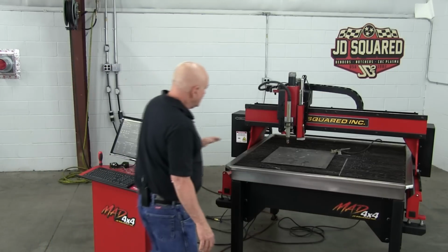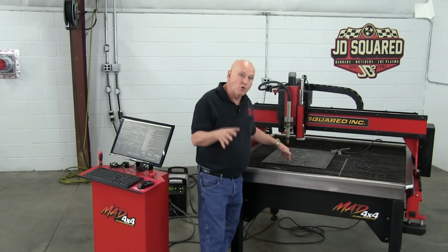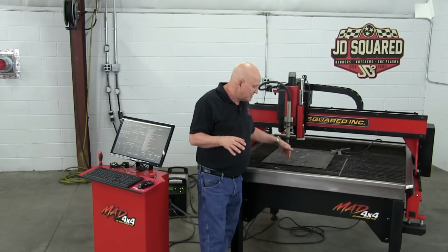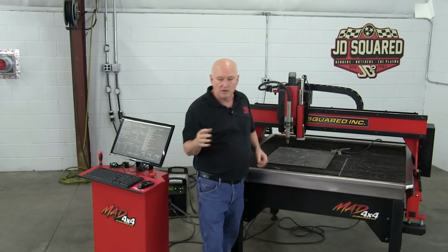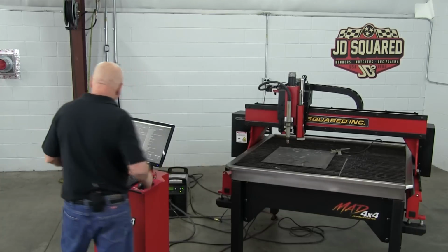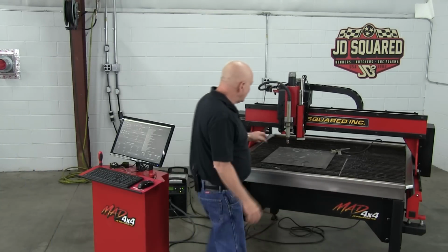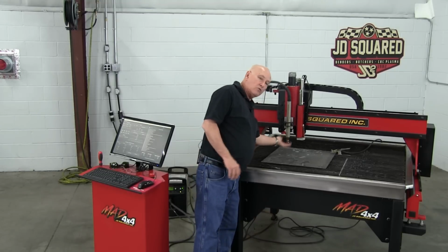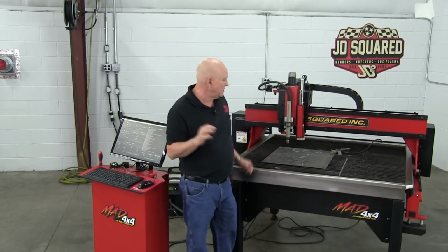Now, if you noticed, when she was wrapping up, it was probing from a 1 inch rapid height. Probing down. That's because it doesn't know where the plate is. You could have flipped up metal, etc. But we added a feature in version 2 called the fast probe height. When you get done cutting, the machine is always going to raise up to your rapid height setting, and in this particular case, it's set at 1 inch.